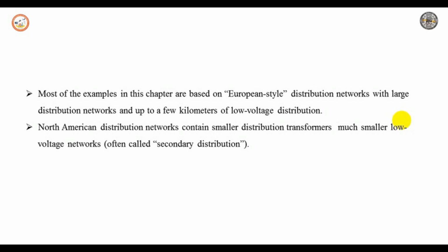Now, the current trend of these PST measurements was taken at a 161 kV substation bus serving an arc furnace load. Here the PST samples are normally reported at 10-minute intervals. A statistical evaluation process is defined to measure the standard, which captures instantaneous flicker. The PLT value is produced every 2 hours from the PST values.